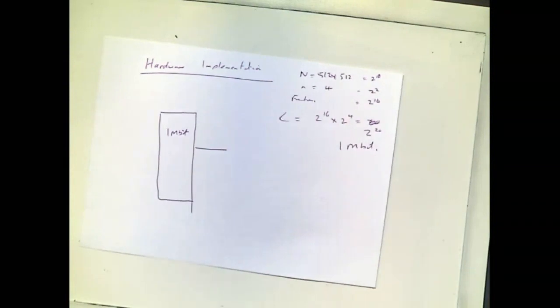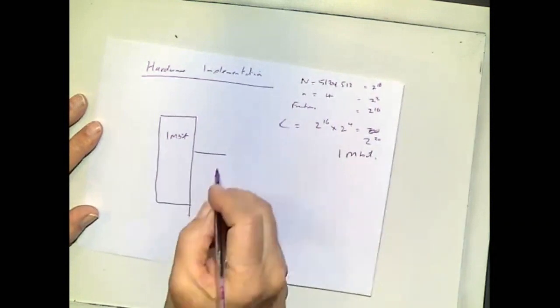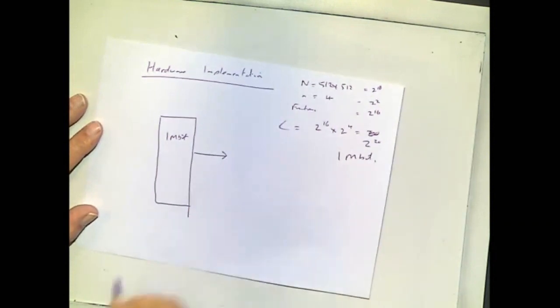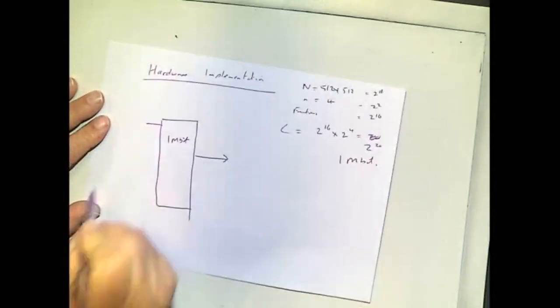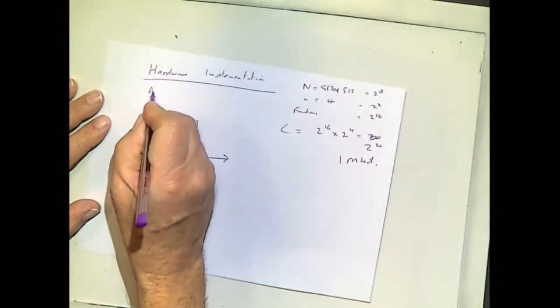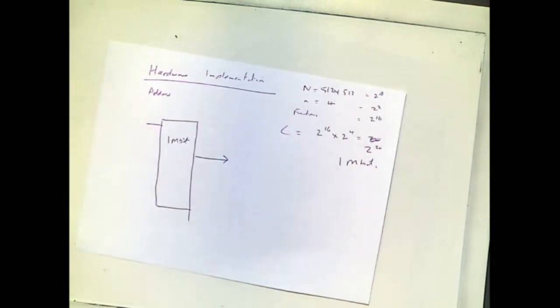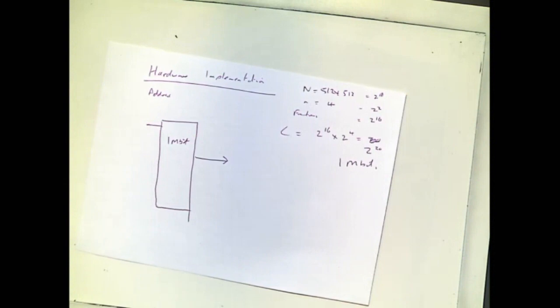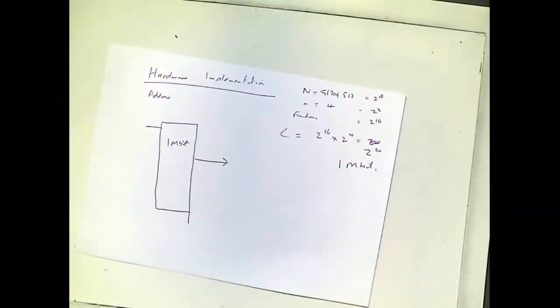Byte organized is interesting, we get parallel networks side by side, but let's go for the single bit organized memory to start off. 1 output. How many address lines? 1 megabit memory, 4 address lines. How many addresses can you get on 4 bits? 16 addresses, and you want 1 million addresses. I think you're a little bit short on the number of address lines.